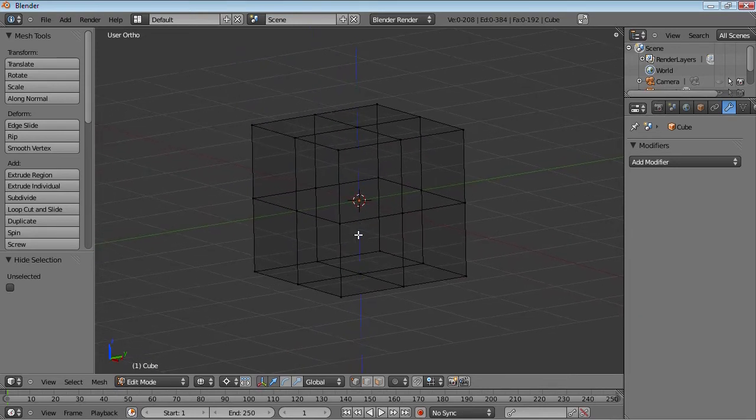It's a technique I used in my Skyward Sword project. I had the controller, the top piece of the controller, and I wanted to hide everything except that piece. So I selected that piece and inverted the selection and hid everything. So it can be used to hide everything that you don't want to keep in your way. So you select everything that you want to keep and then hide the rest using the Invert Selection and Hide tool.